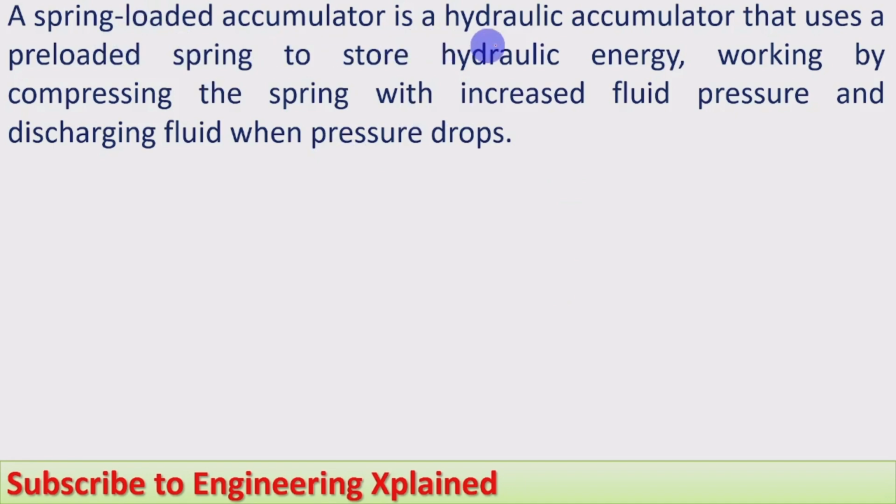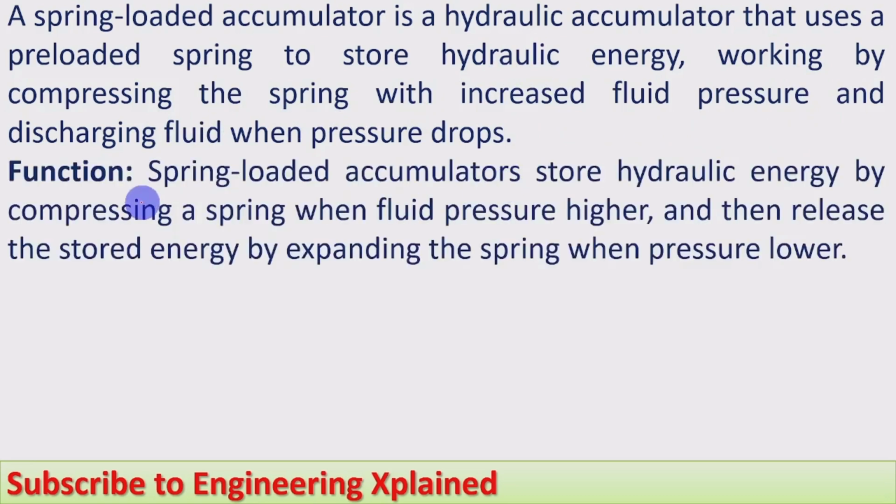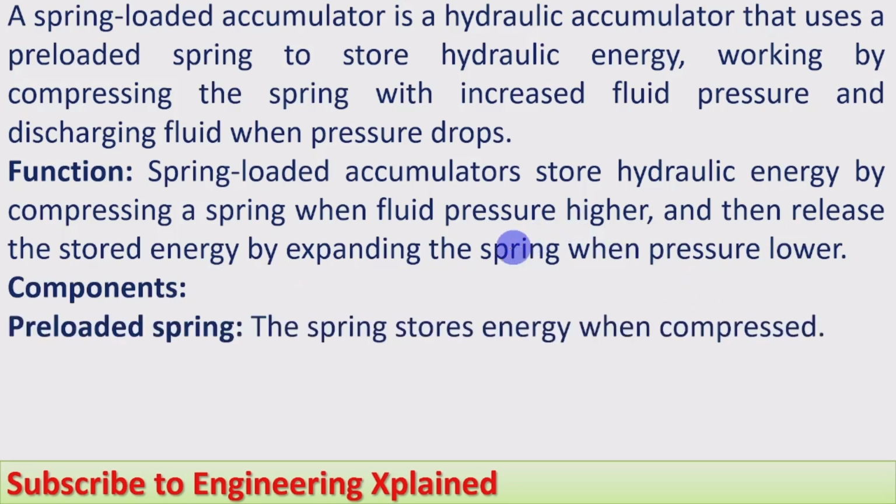A spring loaded accumulator is a hydraulic accumulator that uses a preloaded spring to store hydraulic energy, working by compressing the spring with increased fluid pressure and discharging fluid when pressure drops. Function: spring loaded accumulators store hydraulic energy by compressing a spring when fluid pressure is higher, and then release the stored energy by expanding the spring when pressure is lower. Components: preloaded spring, which stores the energy when compressed.